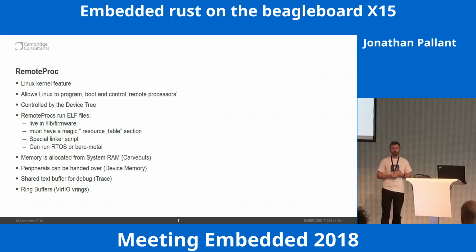And it's the same for the remote proc. There are entries in the device tree that say, I have got these remote processors, load this remote proc driver, and this is where you get the firmware. The Cortex-Ms, the remote processors in this case, just load standard ELF binaries. I don't really have to do anything magic. I just compile a program, place it on the file system in lib firmware.